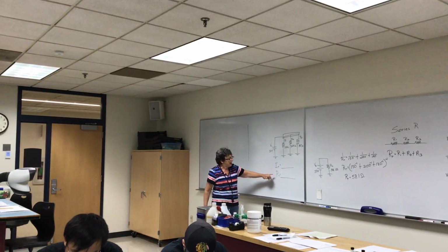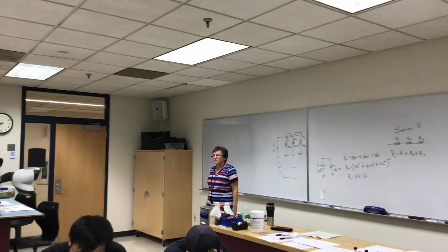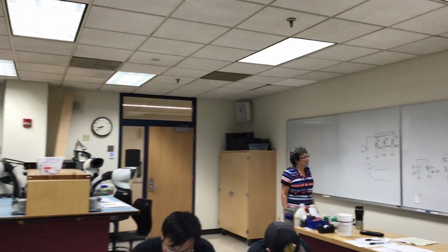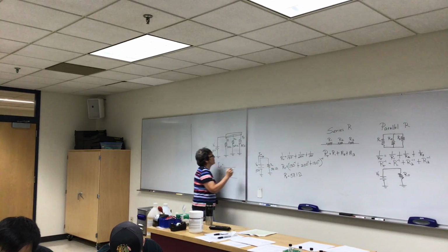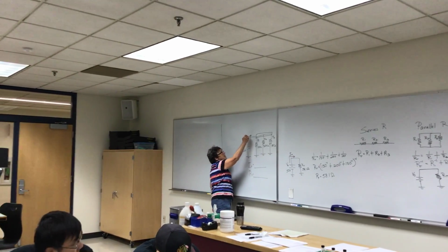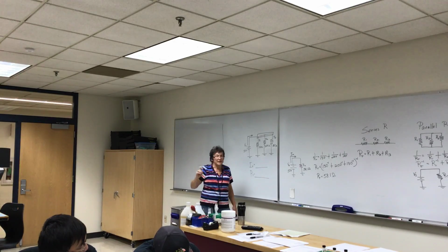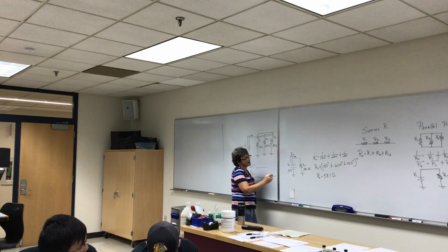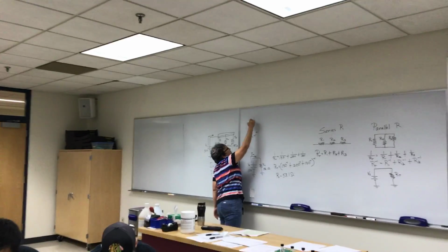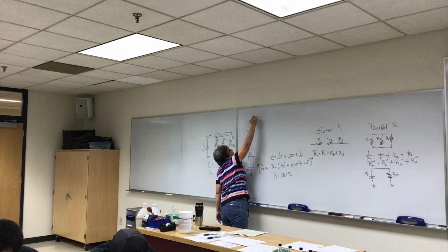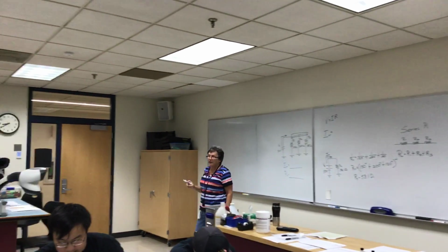We want to find our current and our power. Ohm's law. We can find our I total. And remember, that current is the same in both models, leaving the source. Ohm's law says voltage equals current times resistance, and it's good for a component in the circuit.